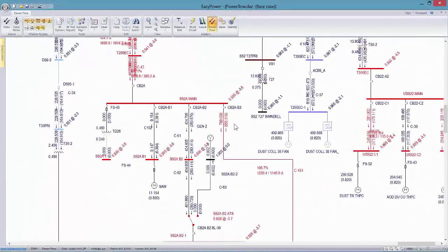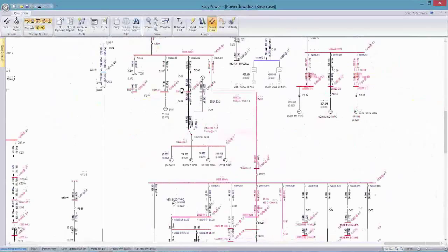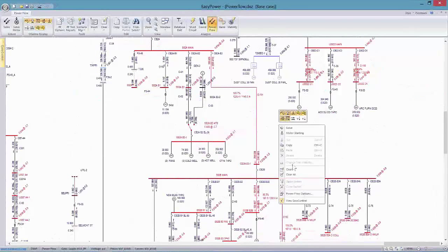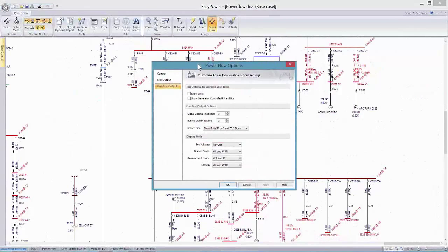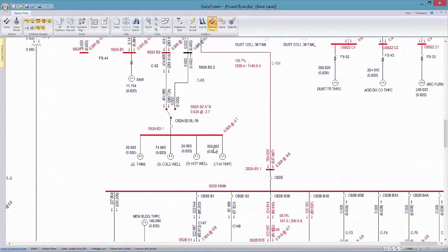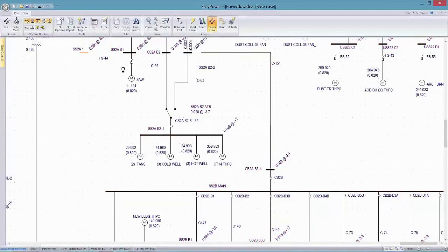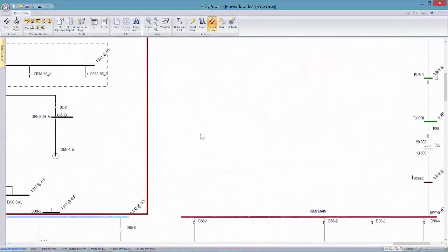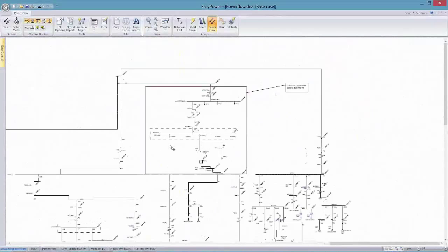Now, the thing that I haven't touched on, and it's probably worthwhile even here, is looking at the display on each of the loads, in which case if we have a motor-intensive environment, we can look at the power factor at that particular point in the loads and the generators. And so what we're showing here is a 359 kilowatt load, the power factor of 0.82 at 100%. Let me take off some of these displays. And when we go back up to the main utility connection,